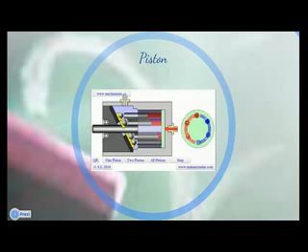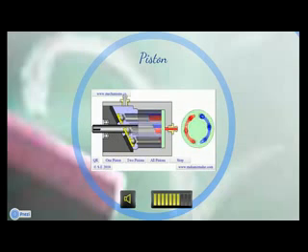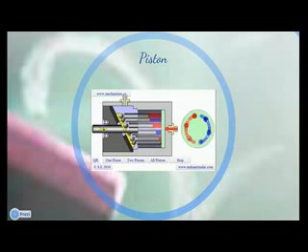Working principles of a fixed displacement piston pump. The device we're going to describe here can also be used as a hydraulic motor. A main shaft connected to a gasoline engine or an electric motor rotates a cylinder barrel.